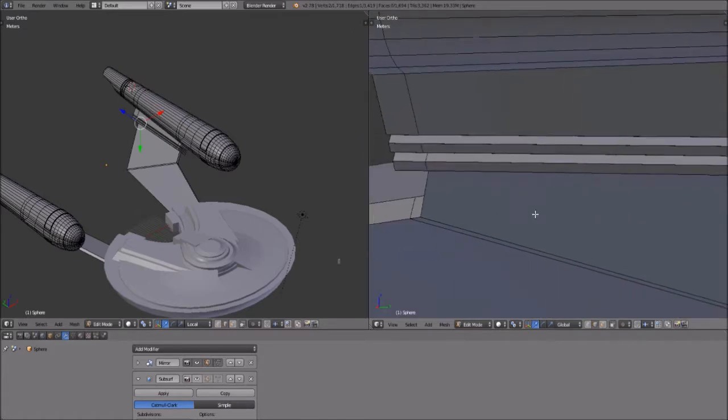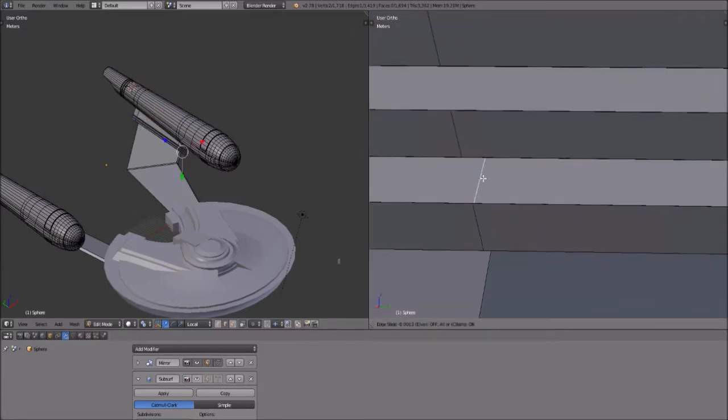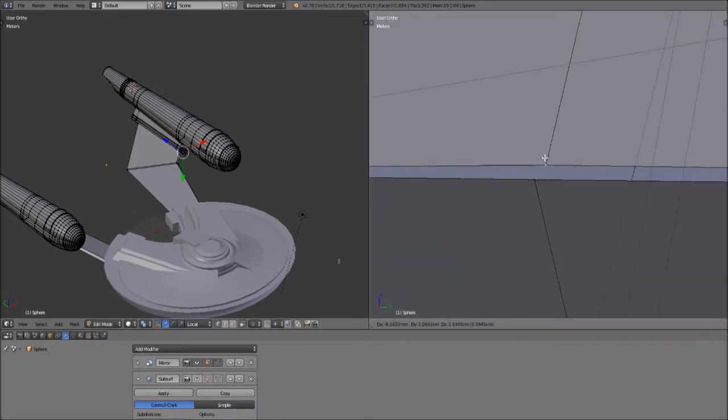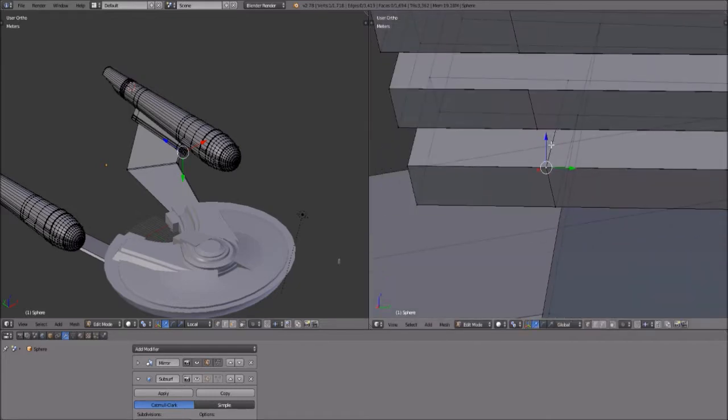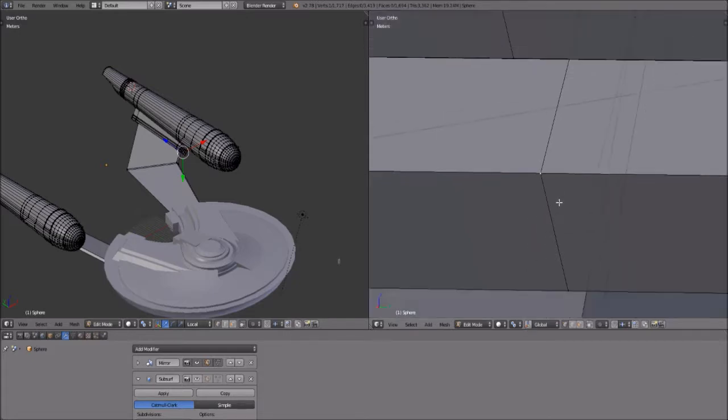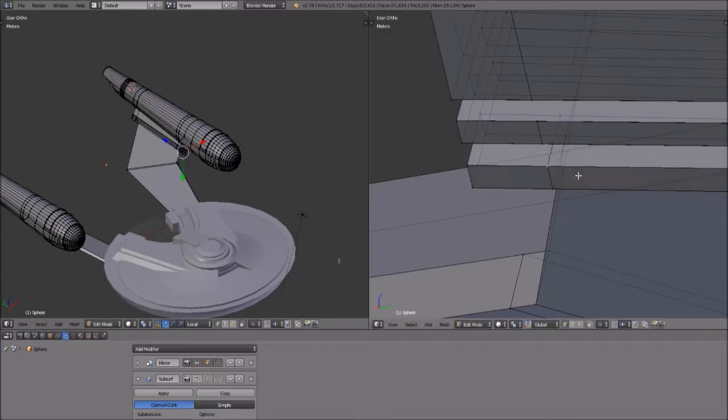And to do the rest of this, I might be cutting out, because it's pretty much just an example of rinse and repeat. So we select that vertice, those two vertices, Alt M. Let's make sure that we're selecting the correct vertex, because I want the vertice on this plane here to meet with the vertice on this plane. So Alt M, at last. Let's get that out of the way, and that should all be good.